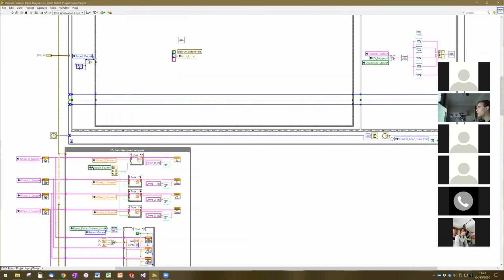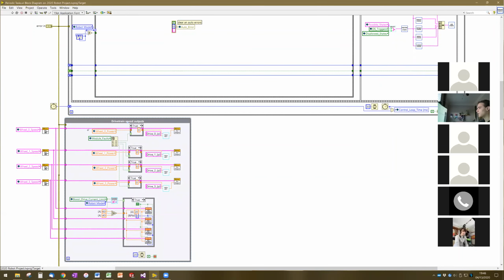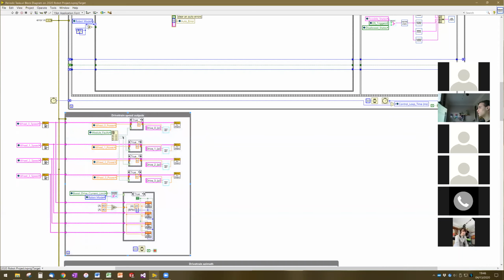And pretty much the only thing that should happen in these parallel loops is to send that determined power to the motor. Now, this year we've added some extra things that do happen in these parallel loops. We've added some safety interlocks to these loops because it's easier to manage them there.